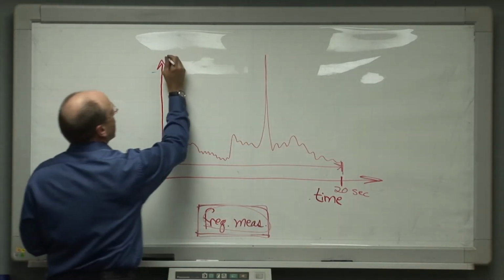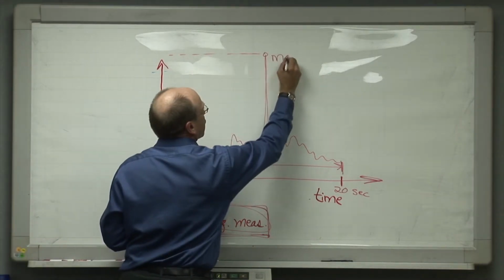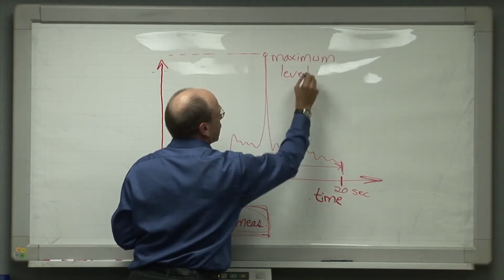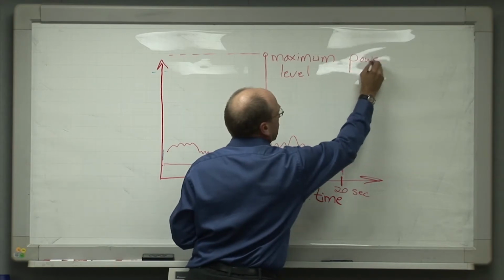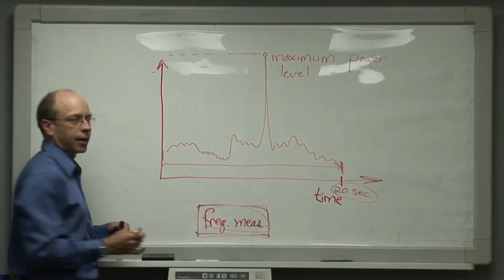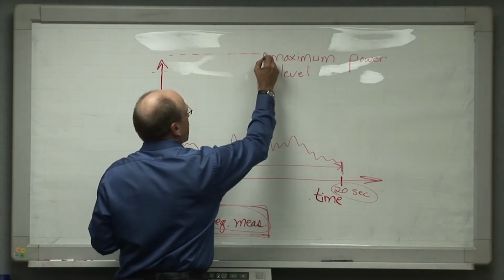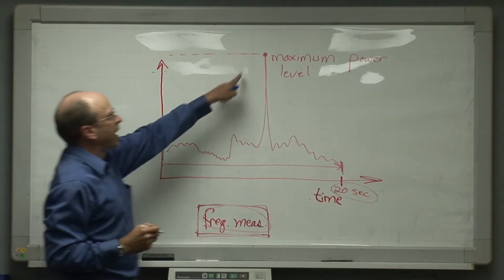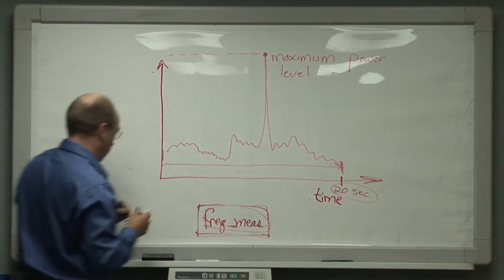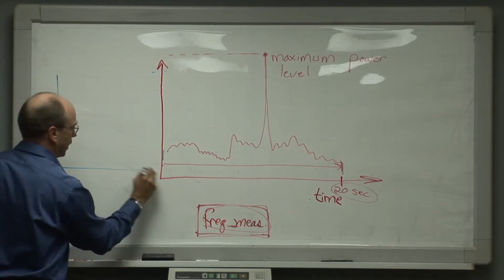like that. Then we know that if we simply always take off of the spectrum analyzer as a data point the maximum power level that occurred within that magic interval of time, in this case 20 seconds, but it could be 10 or 12 or 5, whatever that interval is, then we know that we just measured the maximum amount of power that the radar will put out on that frequency. And we can record that in a measurement spectrum over here, which I'll draw like this.